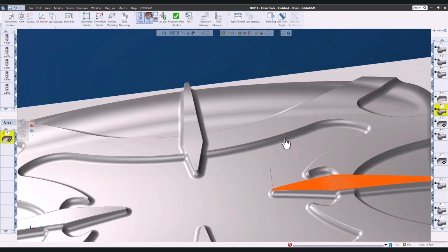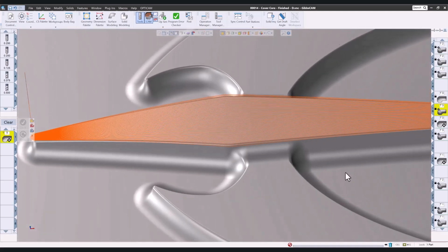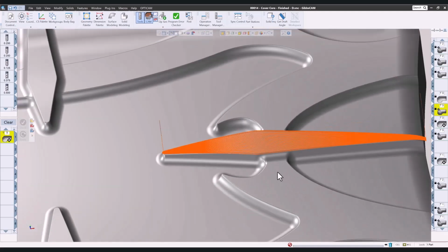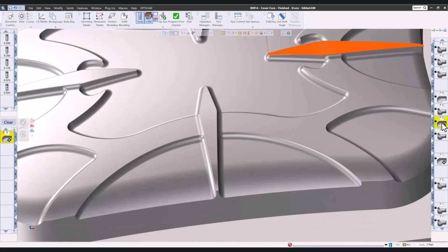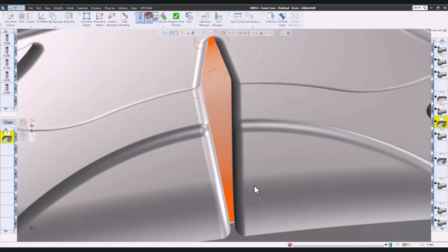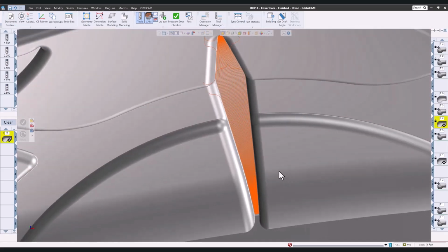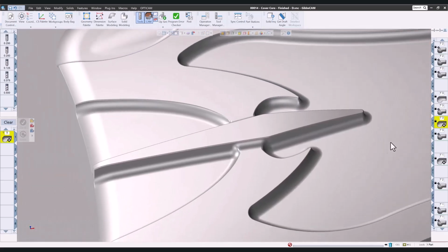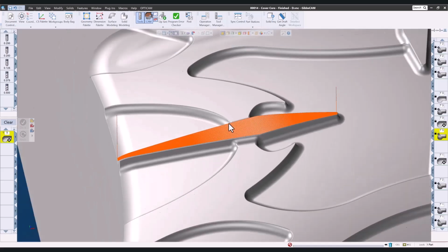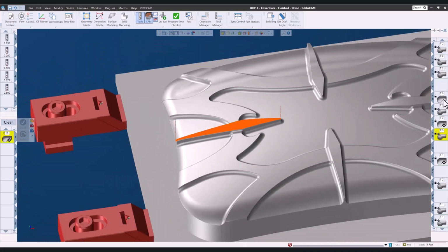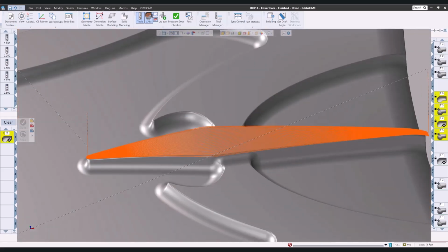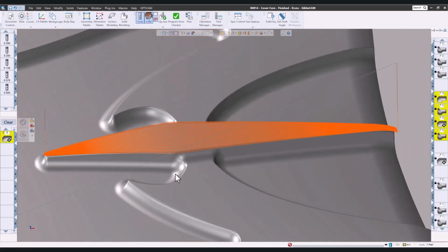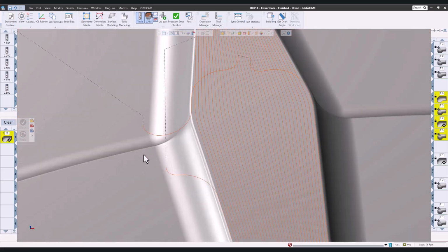I used a multi-axis based on surfaces morphed between 2 curves for this one. I used an advanced 3D in-curve flow for this one. And back to the multi-axis option for a geodesic-based morph between 2 curves for this one. You can see that all these options produce similar toolpath, but with varying numbers of retracts, although none of them have more than just a small handful.